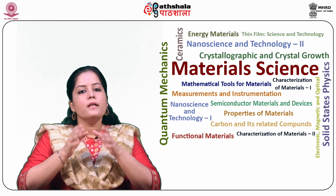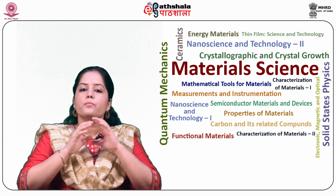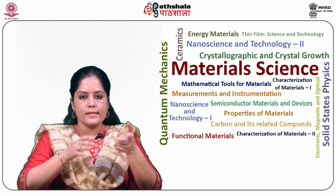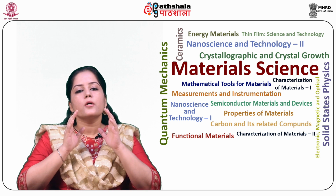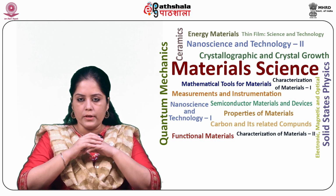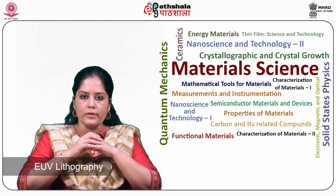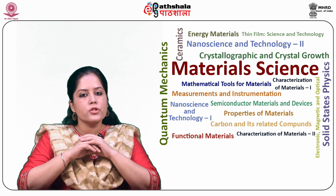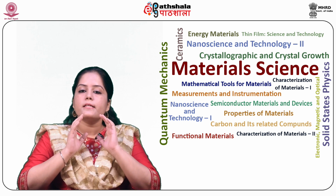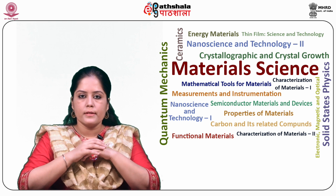So the two main printing modes of these lithographies are proximity mode for X-ray lithography and projection mode for soft X-ray lithography, which is also called EUV lithography. In the following section, we will discuss the essential attributes of these two lithographies.